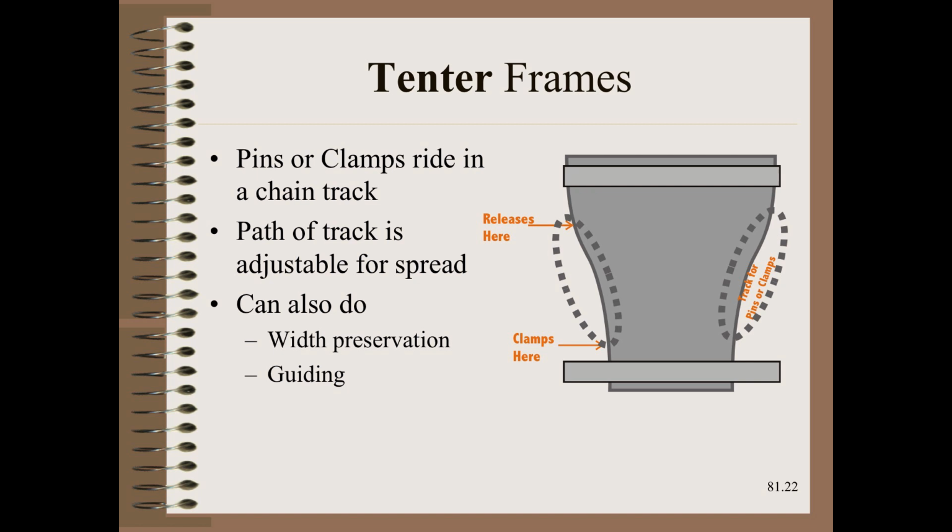Tenter frames are a most powerful spreader used to maintain the width of heavy textiles or even permanently increase web width by many times during biaxial orientation. Here again, we grab a hold of the edges vigorously, in this case with pins or clamps. This spreader would be about as powerful as it gets because you will likely have enough traction to tear webs apart.